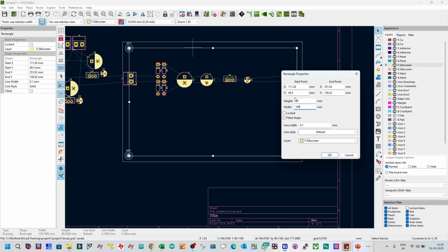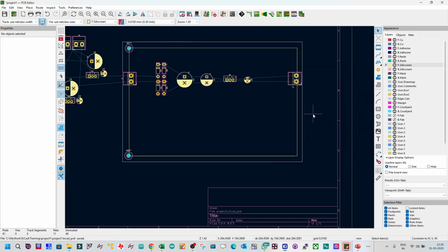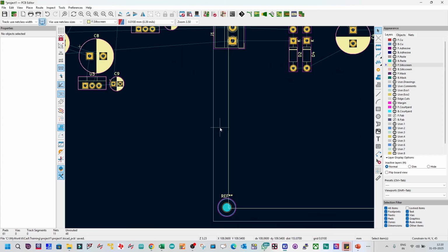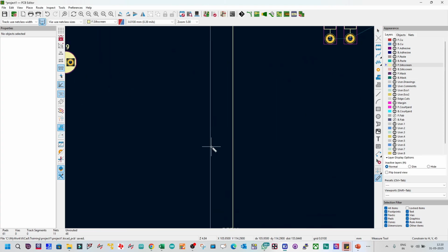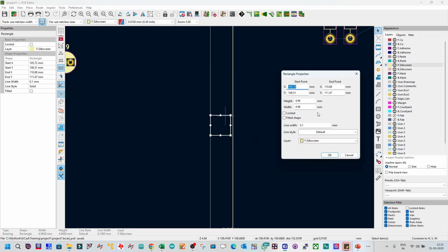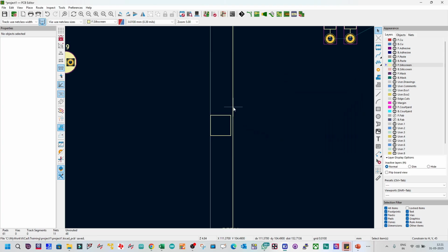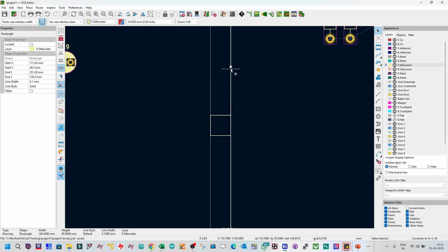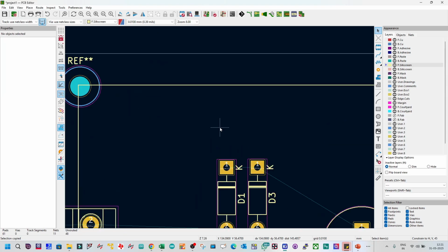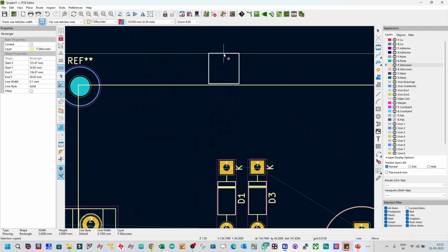So I have a 5 mm boundary from all directions. You can match the top and the sides with a 5 mm boundary. There are many ways you can do this, but the simplest way would be to have a block. Make this 5 mm by 5 mm. So you have to match this guy here. The left side is aligned, and the top side I want to align.